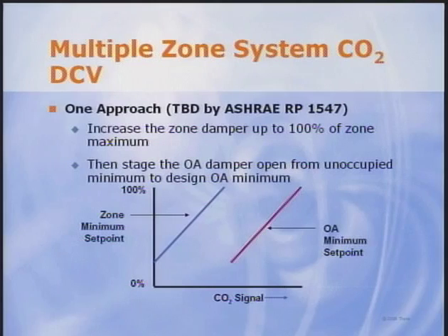Hence, the sequence first tries to ventilate the DCV zones with more supply air, essentially transfer air from overventilated zones, and then calls for additional outdoor air at the air handler. We'll see if ASHRAE's research project corroborates the efficiency of this sequence or finds another to be more effective.